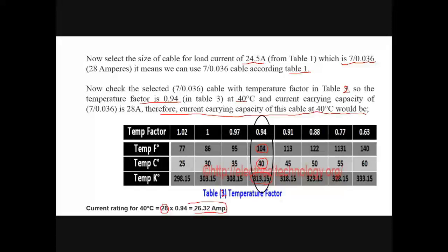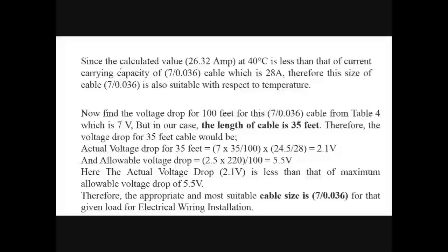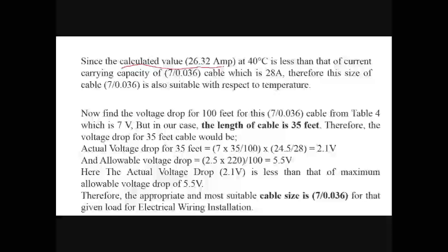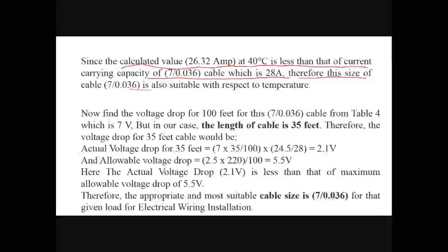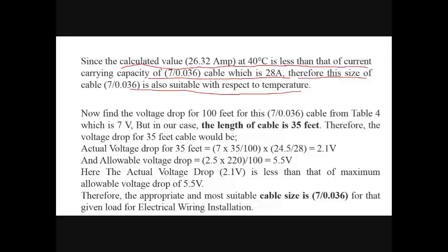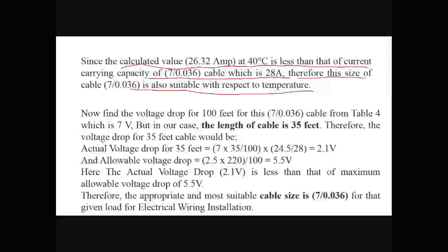Now we have to check again for the 26.32 ampere current. Here you can see I have made the conclusion. Since the calculated value at 40 degrees Celsius is less than the current carrying capacity of the cable, which is 28 ampere, the size of cable is also suitable with respect to temperature.